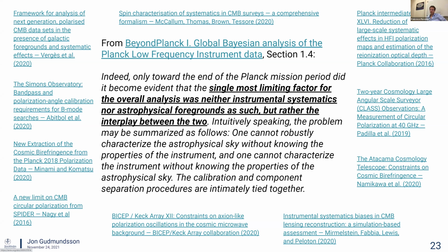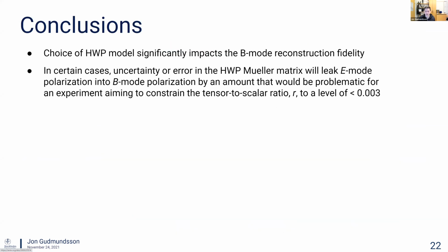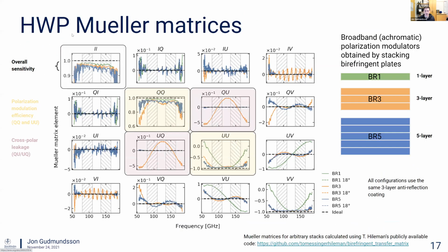Yeah. So what we did, in this paper, no. We used a physical optics beam model at the center band frequency, but that's not because we couldn't do the other thing. It's trivial for us to generate these sub-frequency components and run it that way. The reason we chose to only use a frequency independent beam model, we used a beam model for the 95 and a different one for 150, right? But not across the band. The reason we did that is because we wanted to understand primarily in this publication the impact of these non-idealities and not the beam effects.